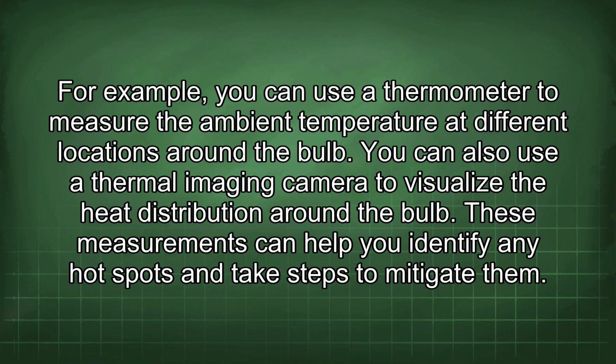For example, you can use a thermometer to measure the ambient temperature at different locations around the bulb. You can also use a thermal imaging camera to visualize the heat distribution around the bulb. These measurements can help you identify any hot spots and take steps to mitigate them.